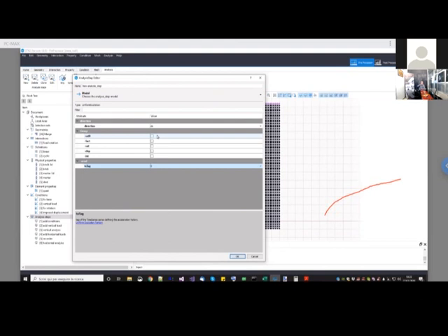For example, if you damage the entire masonry in compression and your vertical load is higher than the residual strength, of course, even if you're using the implex method, you will never reach convergence just because there is no equilibrium point. But those are only the few cases in which the implex cannot guarantee the convergence.